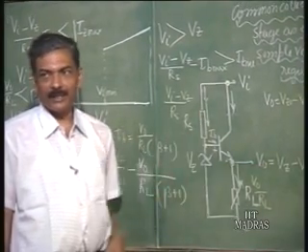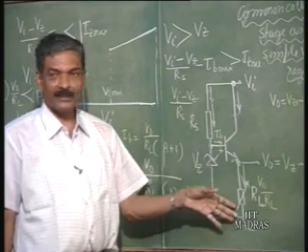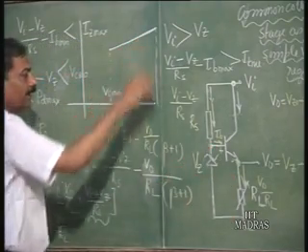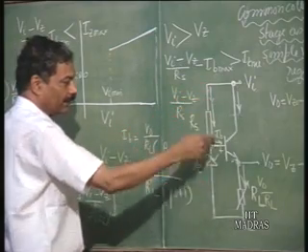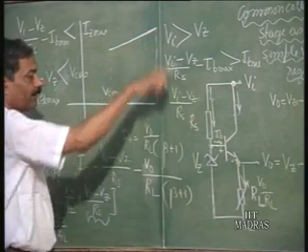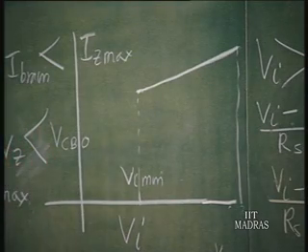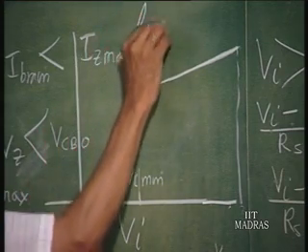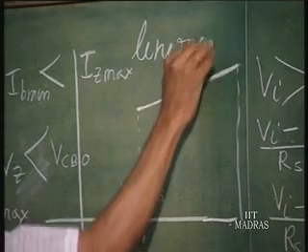This is the direct effect. The load current remaining the same, V gamma will remain the same. So, this is going to increase because Zener current is increasing and Zener voltage is increasing. So, this is increasing because Zener voltage is increasing as V I increases. This is what is called line regulation.